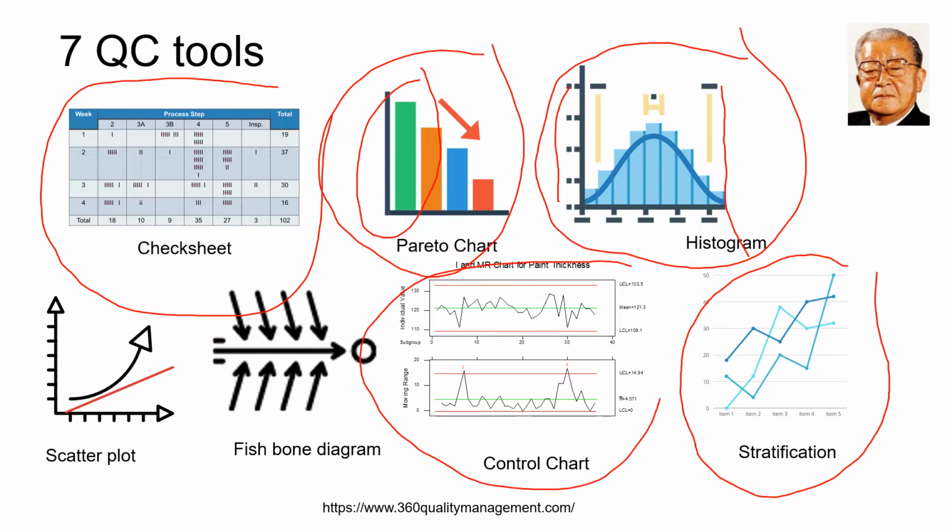The fifth is the control chart, to give us process insights on whether the process is behaving normally or if there is a special cause variation, for which action is needed to eliminate the special cause variations. And also the fishbone diagram, a graphic tool for categorizing the potential causes of a problem in order to identify its root cause to an effect.